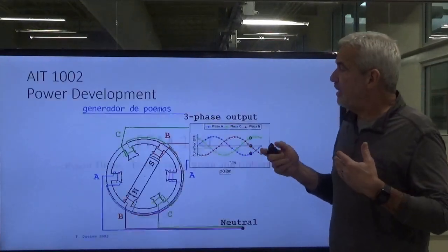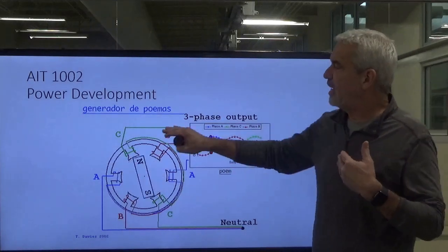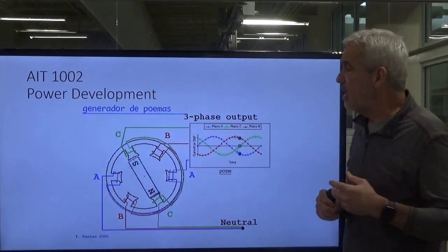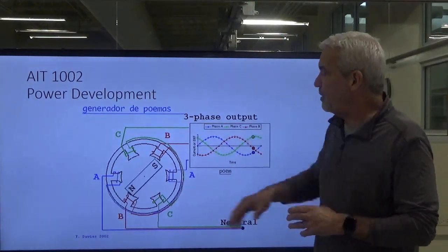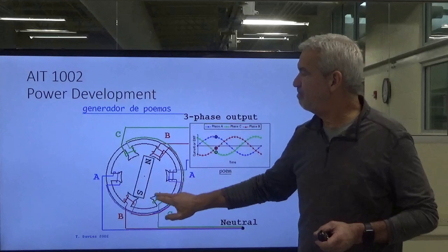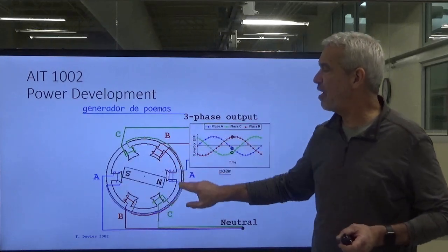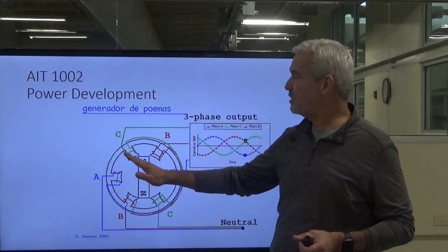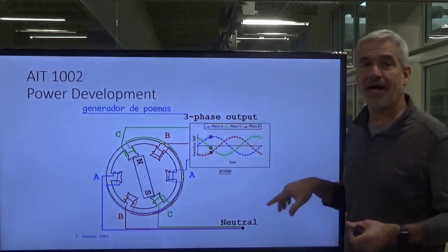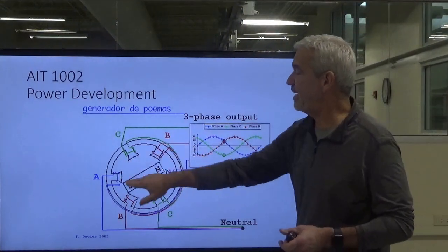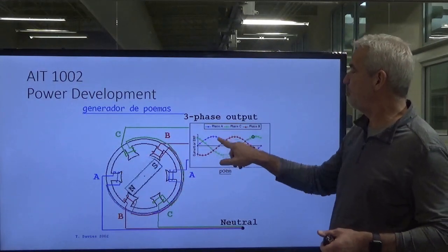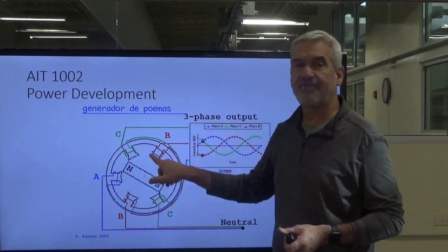So anyway, we backed up to where we talked about our power generation, where our power comes from, our three-phase and our single-phase. We know that it comes from power plants, and we spin a rotor that has a magnetic field in it past these poles, these iron pieces with coils of wire wrapped around them. Anytime that magnetic field passes by a coil of wire, a voltage is induced in this coil, and then we start generating power. In this case, we've got three different phases that the magnet is passing by, so we are inducing three different voltages coming out of our power generator.